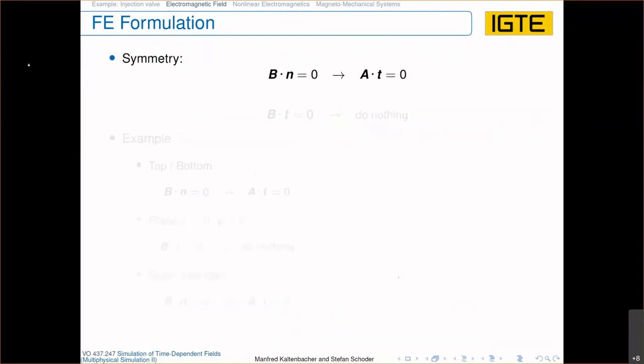Okay. Now, if we have any symmetry, we also want to explore symmetries. Clearly, in 3D, perhaps due to special discretizations in order to resolve eddy currents, whatever you resolve there, you end up with a huge number of unknowns, and therefore if you have some symmetries, not only a geometric symmetry but also a symmetry in the magnetic field, then you should explore it.